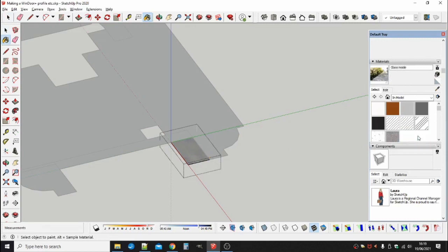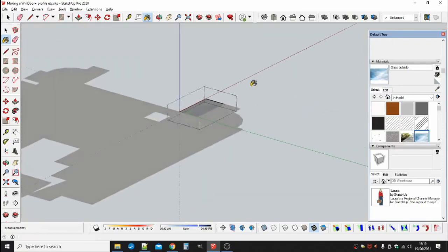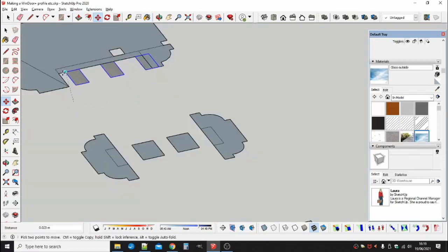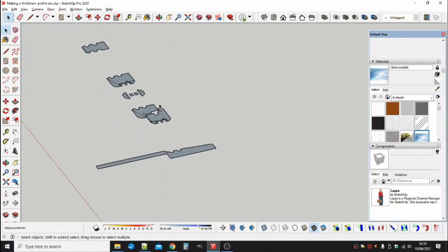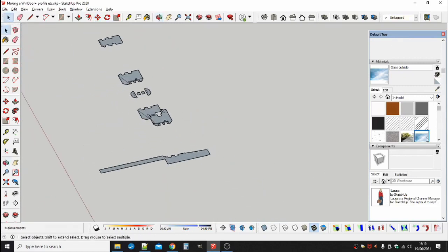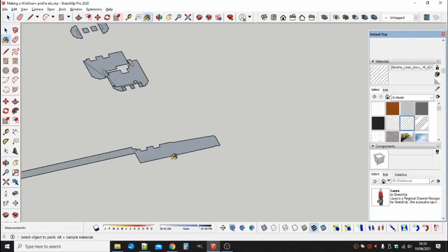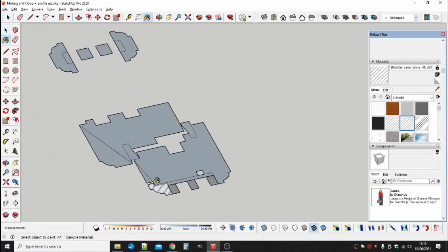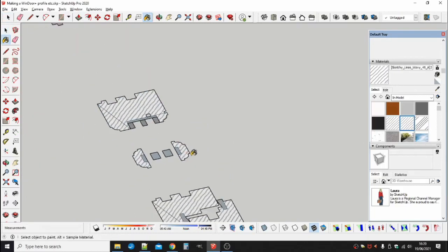This example window is triple glazed, but as stated, the extension will only model the external and internal glass sheets, each as a single face. I nevertheless have shown all three sheets in the profile. This lets the extension know the depth of the glazing unit and retains the designer's intent. Now paint the faces inside the components with the textures which will show when they are extruded into 3D windows.